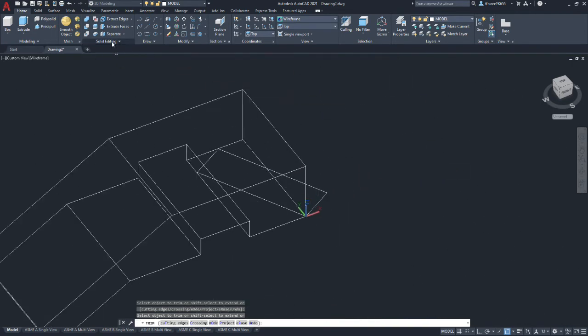All right, because we're going to use the extrude command rather than press pull. What press pull does is, if part of your profile is outside of the part and the other part's inside, it tries to cut and extrude. It can't try to do both. And we want to extrude these two bodies together and then make them one. So in this instance, we want to use the extrude command.